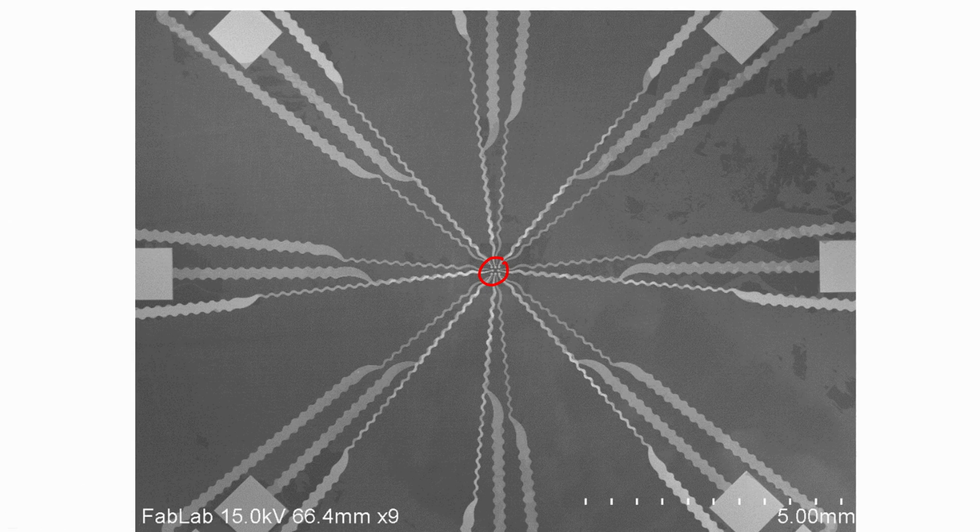Within an area of 1 millimeter we can have two sensors, one is piezoresistor sensor, another one is the electrode. In this SEM image you can see there are two lines that go out of the piezoresistor sensor, one from here and another one from here, and the center one is for the contact pads.